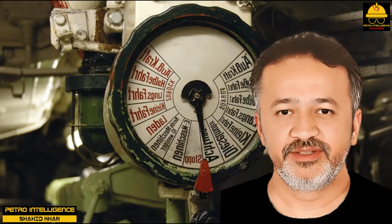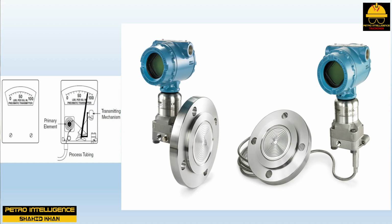Pressure transmitter. A pressure transmitter, as shown in the picture, uses a pressure element to sense pressure and sends a signal to a controller or recorder. Pressure transmitters use all of the primary pressure elements just discussed. Linkage movement allows the transmitter to transmit a signal that is representative of the pressure to a controller or recorder. A controller opens or closes control valves depending on the signal it receives from the transmitter.